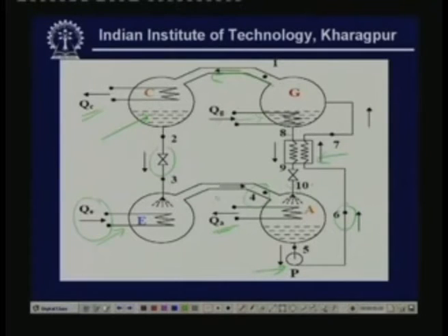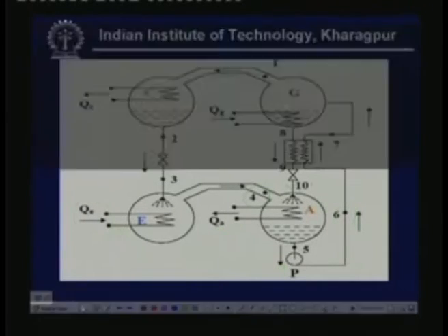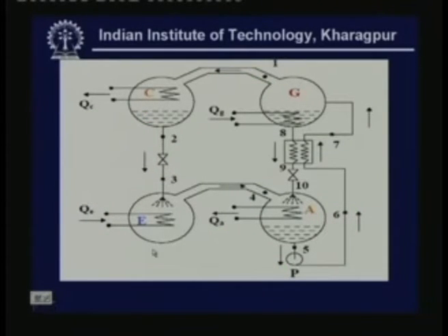And the cycle continues, the vapor goes to the absorber, and the solution, which is now stronger in absorbent and weaker in refrigerant, at point 8 flows through the solution heat exchanger, then the expansion device, and is then sprayed into the absorber, so that it can again absorb the refrigerant vapor. Okay. So, again look at the points. Point 1 is the exit of the generator, where it is pure refrigerant vapor at high pressure and high temperature.